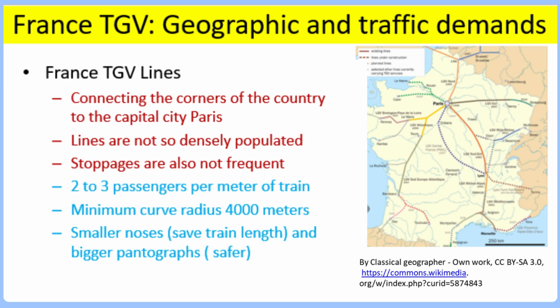French TGV has a lesser passenger capacity, but is more comfortable and spacious, and has a higher critical speed due to stiffer train sets having Jacobs bogies. While Shinkansen trains tend to become unstable around 420 km per hour, TGV holds the world record for the fastest wheeled train, 574 km per hour.